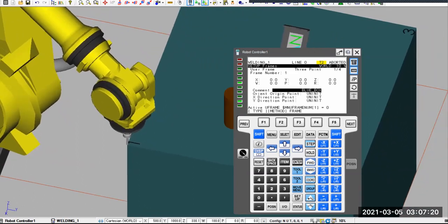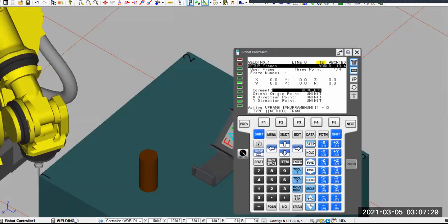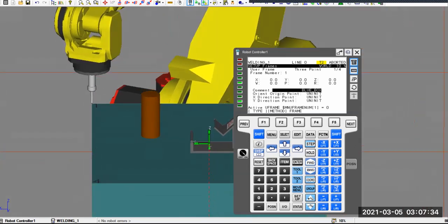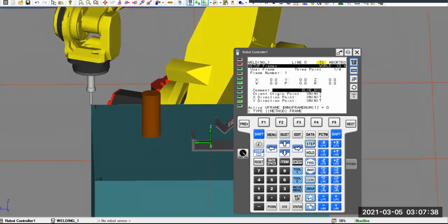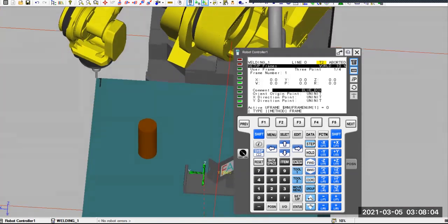So maybe a little bit surprising to you, right? You're supposed to move positive Y, not X, because you may think, okay, this is a catch point, right? If you look at this corner, you may think my back of the hand is here, so that's my index finger, so that's positive X. But actually it's wrong, right? If you remember, I mentioned that the back of the robot is always the part with the connections. On this particular robot, the back of your robot is here. That's supposed to be the back of your hand when you position your right hand rule, right? So that direction is the positive X, and this direction we want is positive Y.